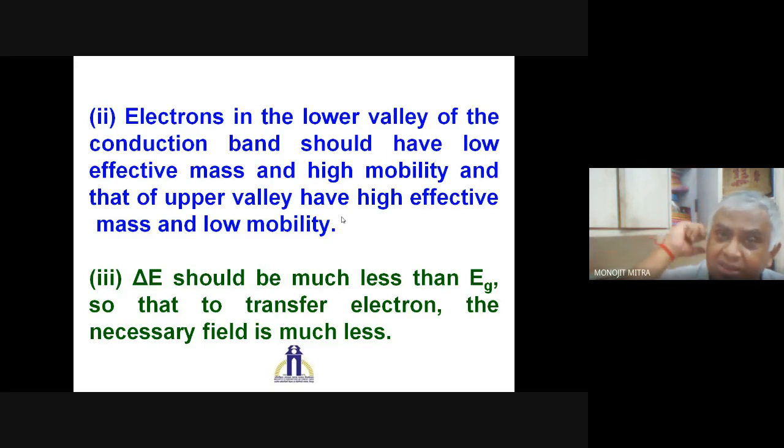So that's why if you take the slope, then delta V means increase in voltage, 3 to 5 volt, or 5 to 7, means change is positive. But if you go through current, you will find it is coming down from 7 to 5, 5 to 3 in milliampere, say. So 3 minus 5 means minus 2. So now if you take the ratio of delta V by delta I, or V by I, you will find it is negative. So that is how it can be negative.